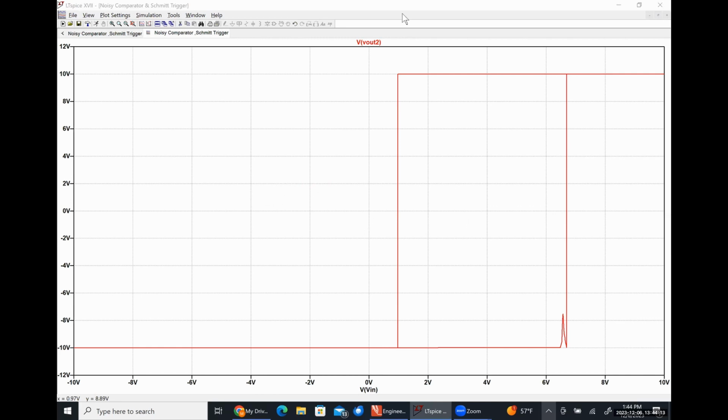So this is a non-inverting trigger. And so what's going on is our input voltage is on the x-axis, right? Our input voltage is ranging from -10 to +10 and then going back. So we start off with a negative input voltage. And our output is low, our output is low until we hit this point. This is our upper trigger limit. So when our input voltage exceeds our upper trigger limit, our output changes from VCC minus up to VCC plus.